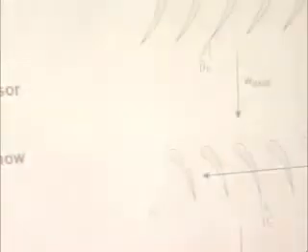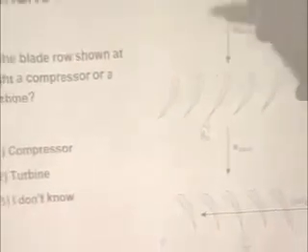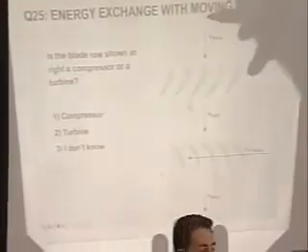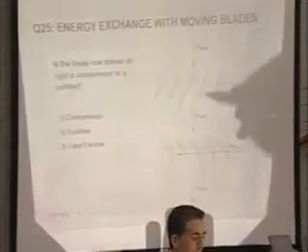Right, so just follow the rules. Let me show you how to do this. I wish I had a little bit thicker pens, but I think you'll be able to follow along. First, this is the whole velocity vector coming into this blade row. There's nothing more. It's pure axial flow coming in. And then I say the flow leaves that stationary blade row at this angle, beta B.